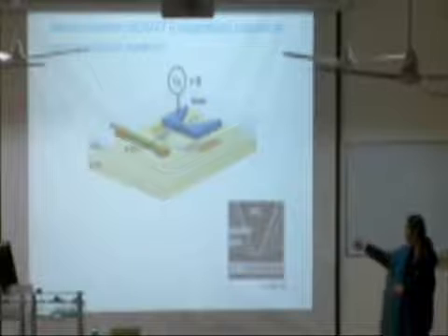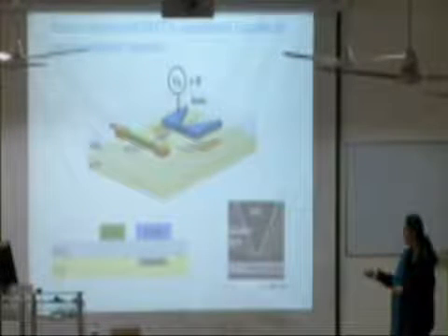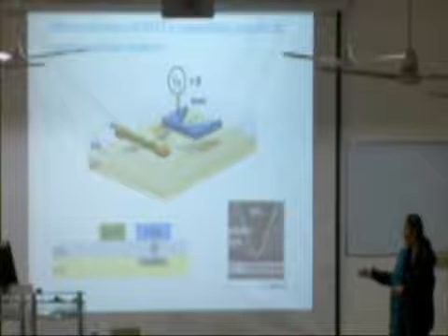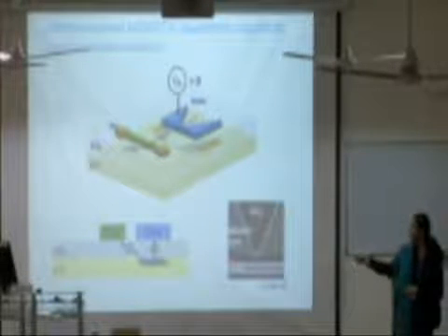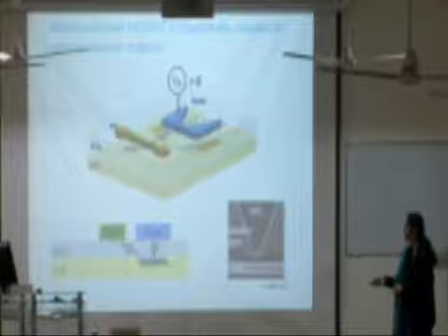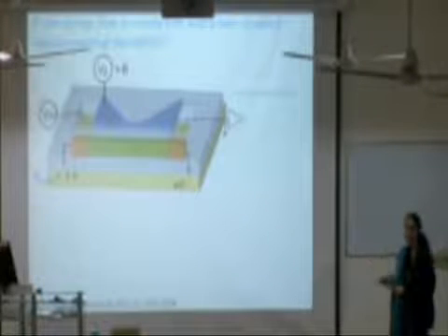If you look at a cross-section along this black dotted line, this is what it looks like. The gate is capacitively coupled to the inversion region, and so is the amorphous germanium strip. And our measurement relies on this capacitive coupling. So how do we probe transport in this material with the MOSFET?